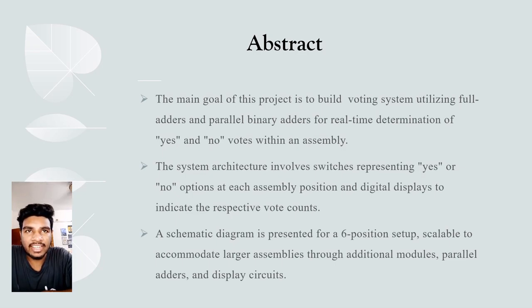The system architecture involves a switch representing a yes or no option for each assembly member, and displays to indicate the respective vote counts. A diagram is presented for a six-member setup, which can be extended to a longer assembly through additional modules, parallel adders and display circuits.